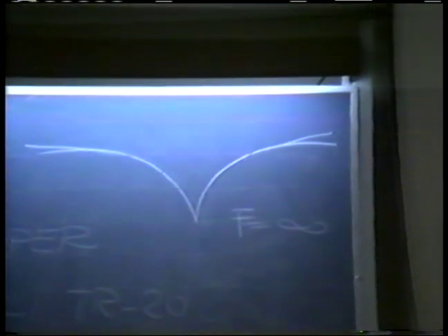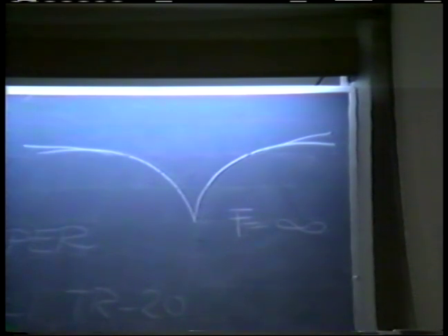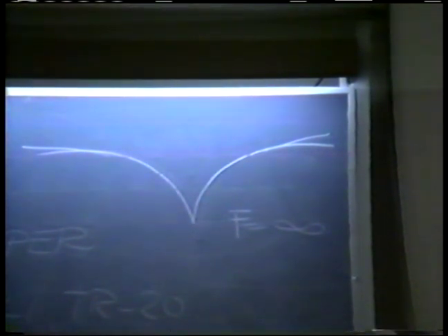It's an infinite value. So you cannot, under any circumstance, have instability with such a cross-section, because it's just not going to be there. The hydrodynamics tells us it's not going to be there. And that is obviously the reason why you don't have roll waves in flows that cover the floodplain.